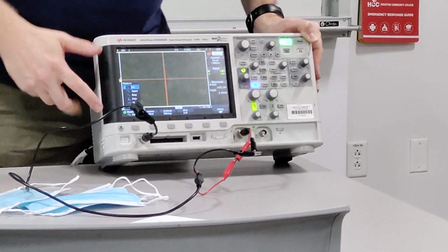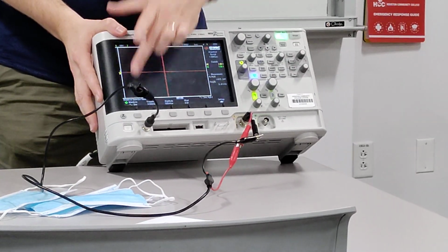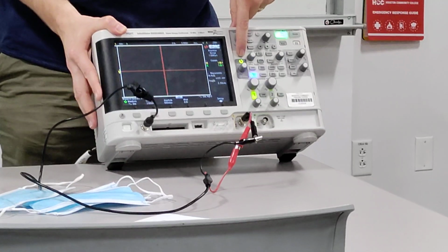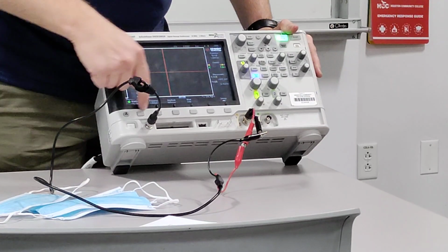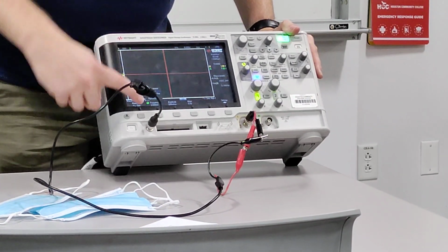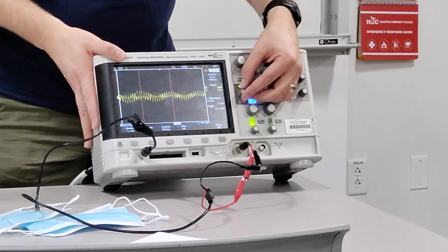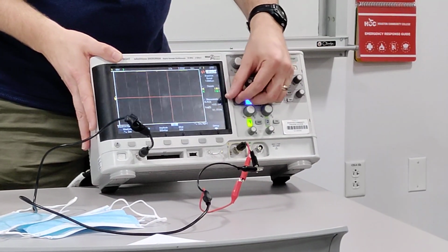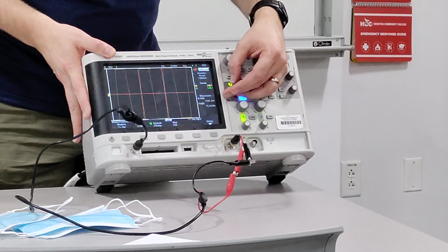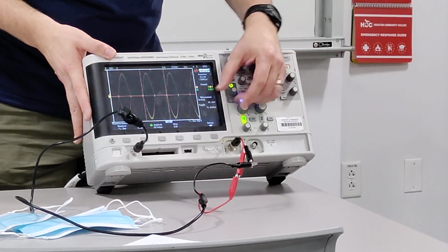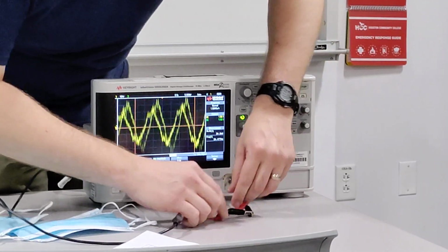There's also a little circle arrow icon under that button right now. That always means that this knob here with that same icon will control that. So I can go through and change the waveform through that. If I want to change frequency or amplitude or offset, I just hit that button and then I have a little yellow circle icon next to it and I can adjust it. So now I am lowering the frequency so we can actually see something. And then I'm going to lower the amplitude so it's not so cut off. All right. And now we have a slightly noisy signal, which is fine.